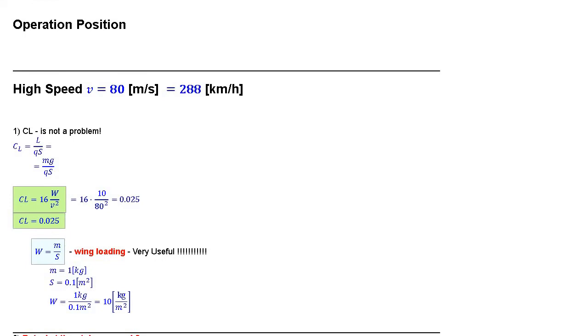Before starting the simulation, we should answer a few questions. The first remark is that there is no perfect airfoil, but there is the best airfoil for the given operational range. So we have to choose the operational range. Let's say we wish to fly at this speed, and for the plane to have the minimum drag at this speed. So to fly efficiently at this high speed, we have to have an airfoil having the minimum drag at this speed. That's a simple requirement.